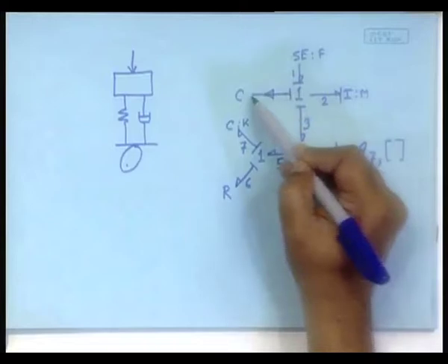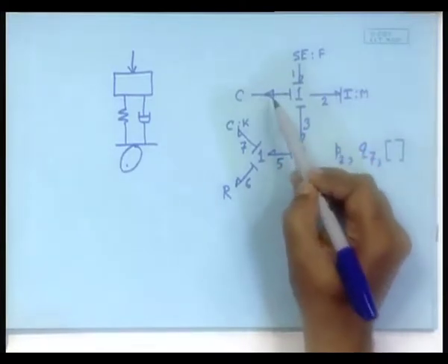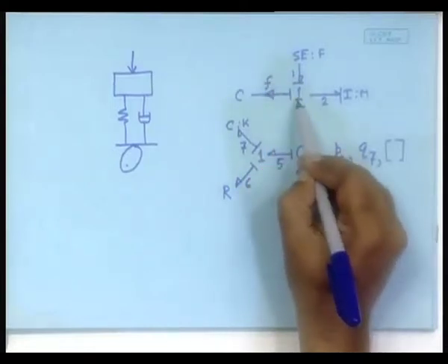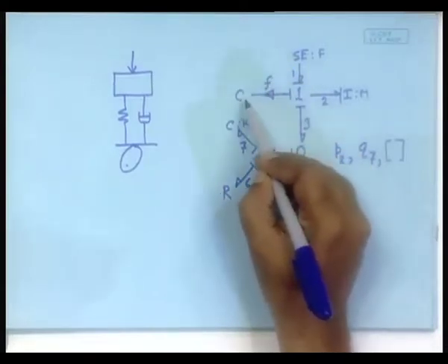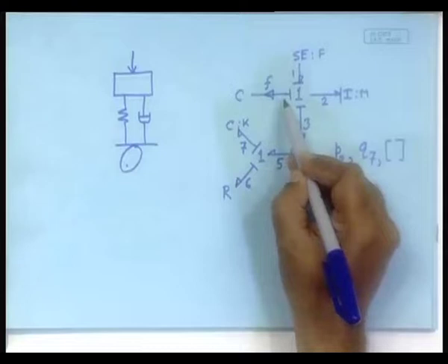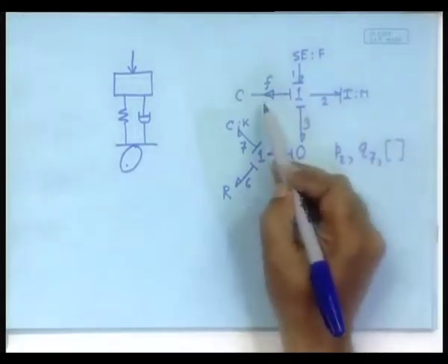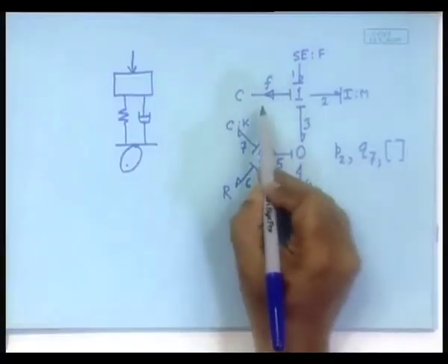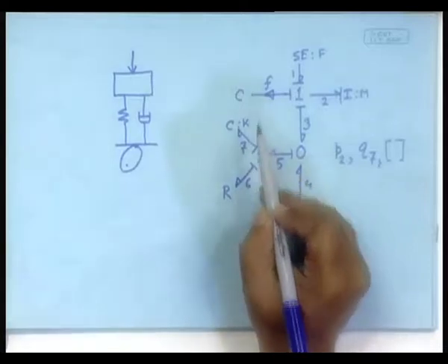So, we will have it, but what does it receive actually? What actually flows through this bond? The flow. It receives the flow information and it generates the effort information. It generates the effort information means that is why it becomes a state variable Q. So, you get it. So, this particular addition is the activated bond.